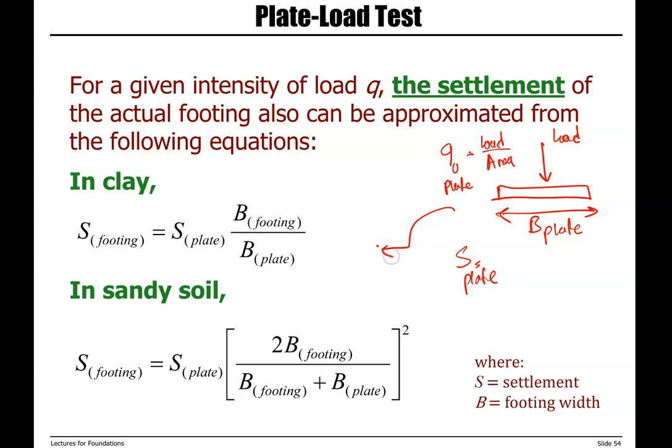Now we have the formulas to find settlement of footing when we have settlement of plate. So in clay, settlement of footing is equal to settlement of plate times width of footing divided by width of plate. If we have sandy soil, this is the formula that you need to use.